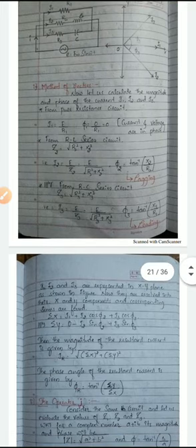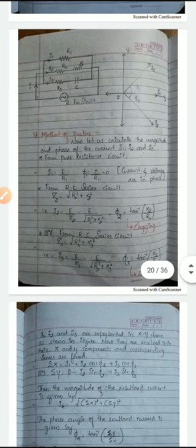Because we know that phi is always the imaginary part divided by the real part. Here in the equation for I1 there is no imaginary term, therefore the imaginary part is 0 by R1, which is nothing but 0. So phi equals tan inverse of 0, which indicates phi is 0 only, that is, both current and voltage are in phase. Another thing is that current I1 is flowing across resistor R1, a pure resistive circuit, and in a pure resistive circuit both current and voltage are in phase.